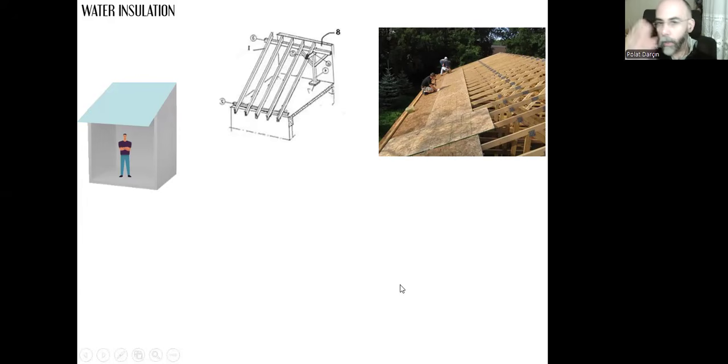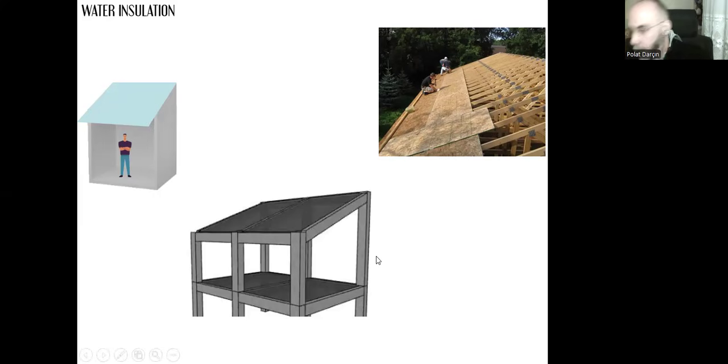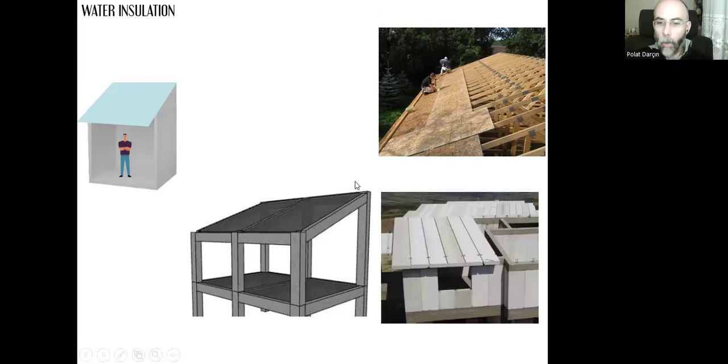Instead of creating load transferring roofs using timber or steel pieces like rafters, purlins and studs, we can have inclined reinforced concrete floor slabs, or we can have AAC panels. Once we do that, we already have a smooth surface, and we can apply the bitumen sheet over these inclined surfaces.